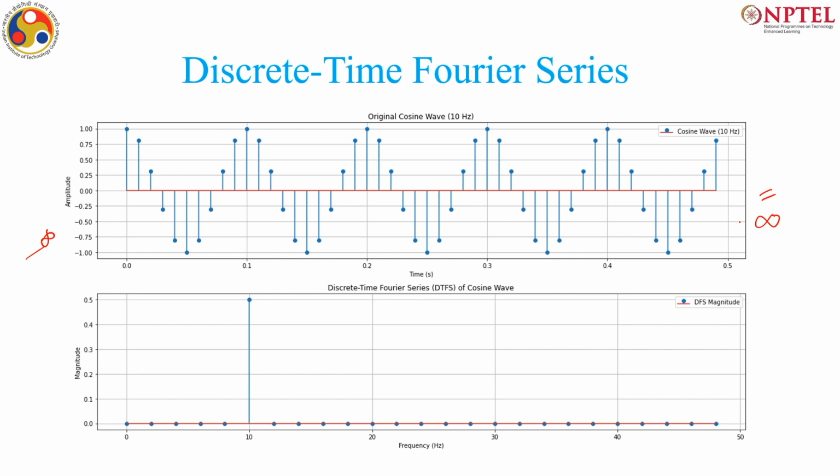If I decompose it into the Fourier series, we will see that it has only one component, or rather a component at 10 and minus 10, because this is a 10 hertz signal. This is mapped back to the original continuous domain spectra, where the frequency is in hertz, just to demonstrate how I can represent this cosine wave of 10 hertz with just one value.